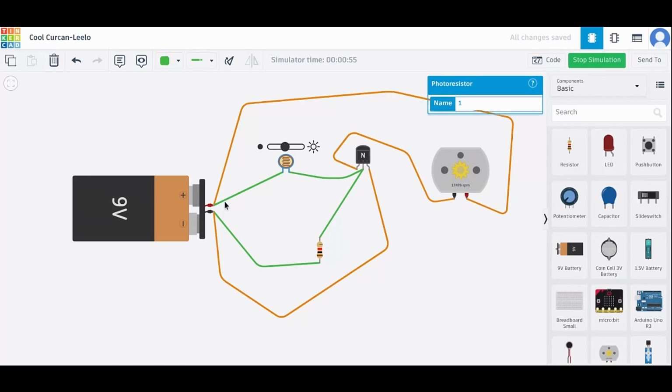Okay. So first terminal, second terminal, and the third terminal. You could see it as a potentiometer, or you could also see that as a voltage divider. So now we have the ability to control the voltage at the base and, in turn, the current at the base. So we have the ability to turn the switch on and off.